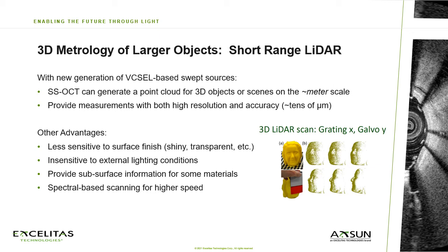Some advantages of using swept source OCT technology include insensitivity to surface finish, which can be problematic for triangulation-based scanners, insensitivity to lighting conditions, which can be problematic for structured illumination and photographic scanners, and higher resolution and accuracy than time-of-flight laser scanners.